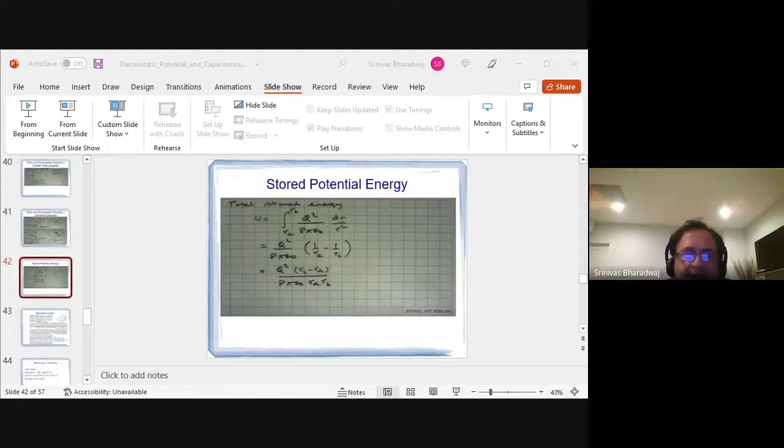Okay, the dielectric constant is K, and it is just a multiple of epsilon naught. Instead of epsilon naught A by D, we will then introduce epsilon naught K times A by D. So that K is called the dielectric constant, and it is typically 1 plus psi, where psi is this variable we introduce: electric susceptibility.